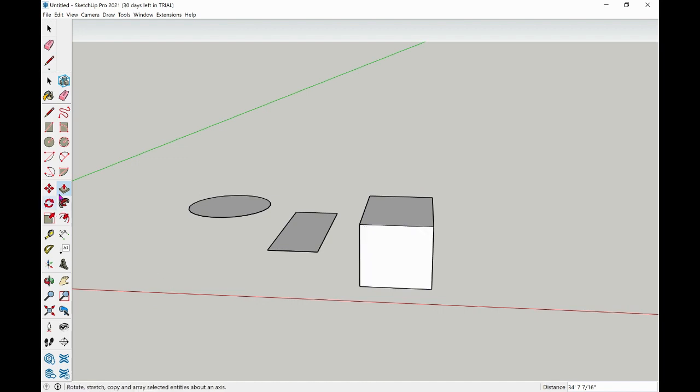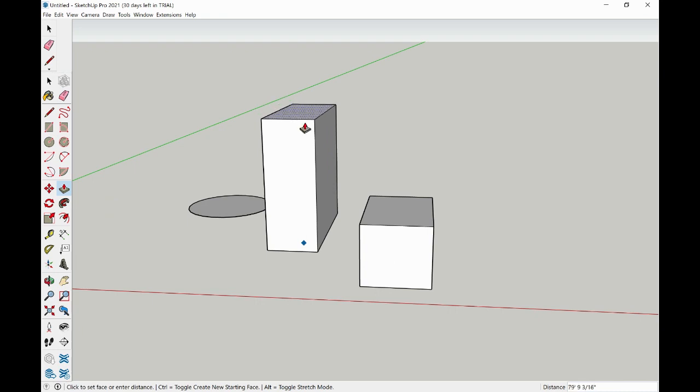Now, again, you can select the tool first and then go to the shape, and press escape to bring us out of the tool. Or you can go to the arrow, which is your selection tool, and select the area you want to push-pull first, and then go to the command and do what you need to do with it. For this, I am going to either pull this up or use my mouse to bring it over to the edge of another shape at a height that I already like and snap it right to that same height by selecting an endpoint or an edge line.